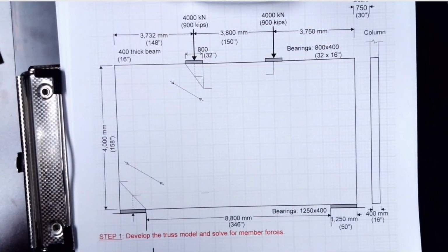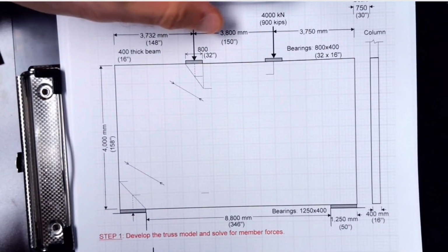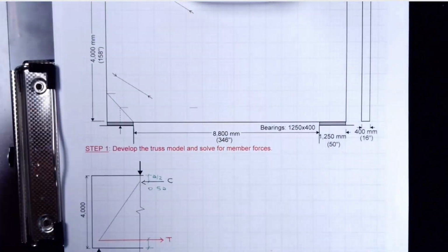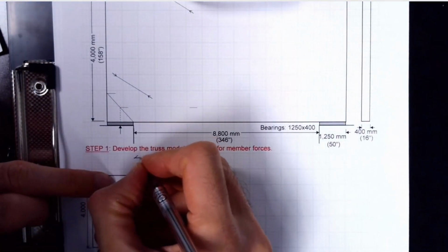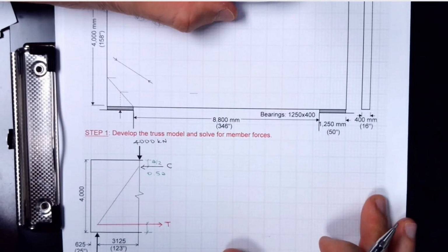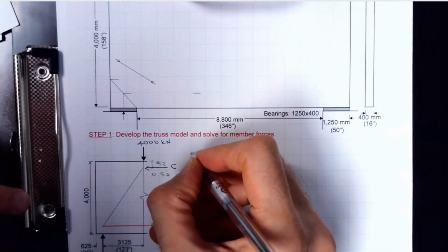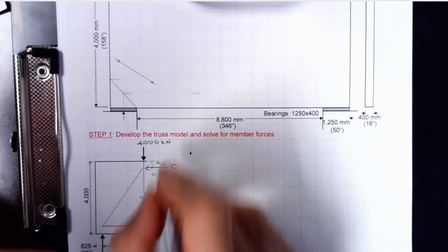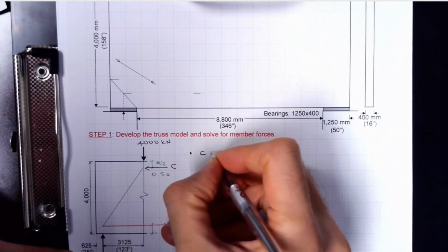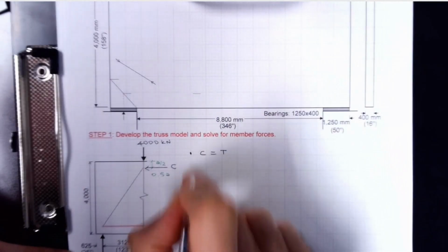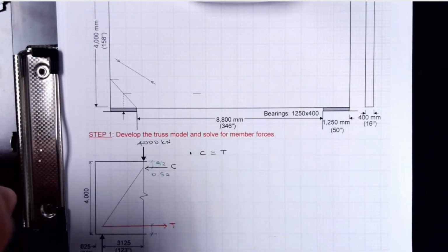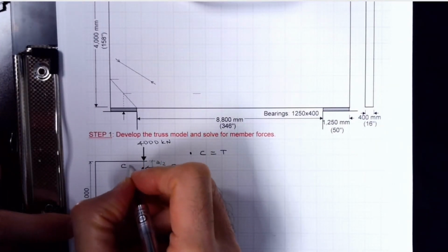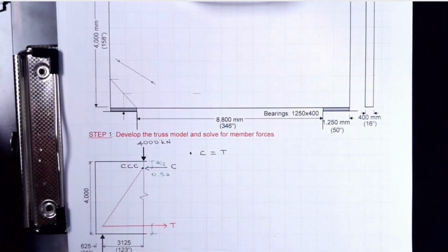As you can see, 900 kips applied at the top. So let me write this, 900 kips. I'm going to use some basic mechanics to make an educated guess for these two distances. I know that compression would be the same as tension, these two. If you look at the nodal categories, the node at the top would be compression, compression, compression.